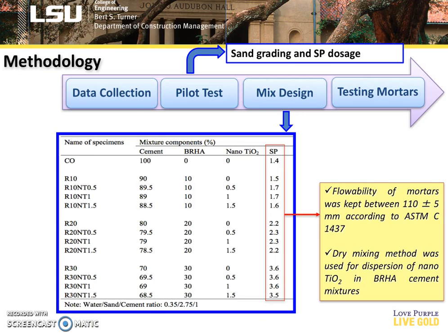For my methodology, I had data collection. I did some pilot tests to get the sand gradation. Since the workability and flowability are constant for all mixes, I did some pilot tests to get the dosage of the superplasticizer for each mix design. Then I started my actual mix design.